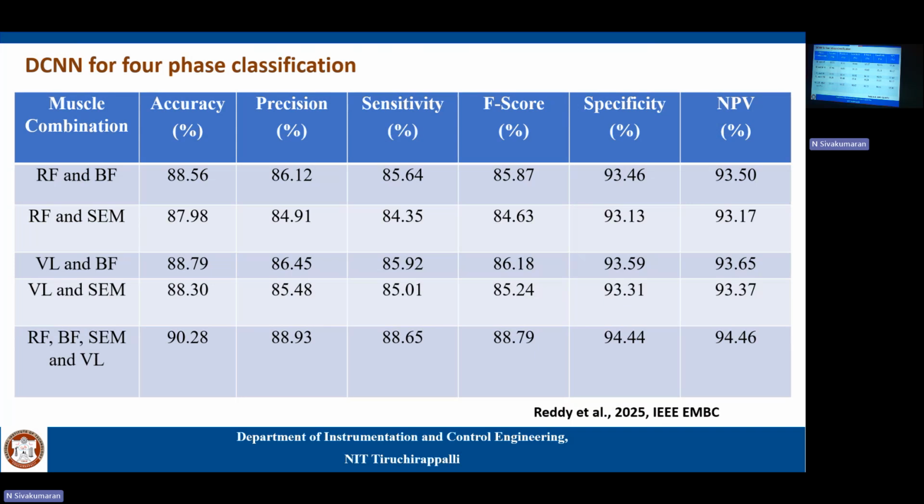So what does this 10% signify here? I want to actuate my knee with EMG. Let's say 100 steps. What this model tells is that if you take decisions based on EMG, for every 100 steps, 90 times your EMG model gives the correct result, and 10 times it fails, which means in every 100 steps, my patient would fall 10 times.